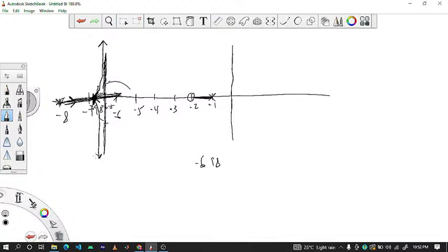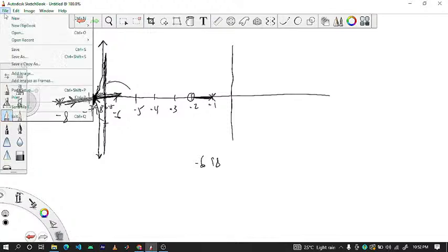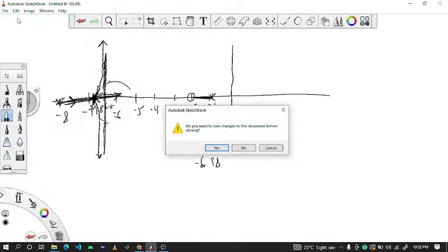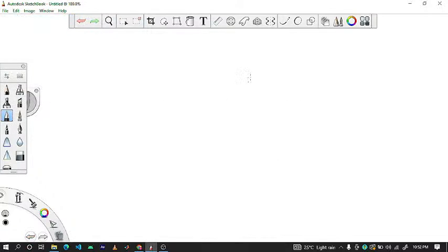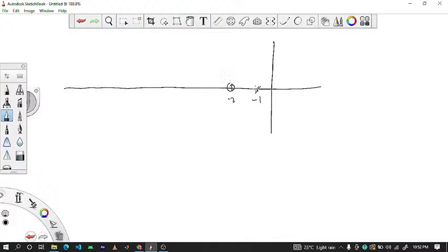Let me make a very neat sketch. I'll leave a wide gap between the minus 7 and 8 so that you see well. Okay, so we had it like this. Minus 1, minus 2, 0, pole. Root locus from pole to 0, done. Okay, let me see. I have minus 6 here. I have minus 8 here, right? Let's say I have minus 7 here. We got our centroid to be minus 6.5.